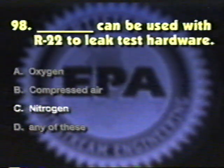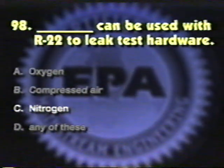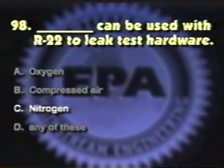The answer is C. Nitrogen. Nitrogen can be used with R22 to leak check hardware. Mixtures of nitrogen and any other CFC, HFC, or HCFC except HCFC-22 are subject to the prohibition on venting. That means it is illegal to vent them into the atmosphere.